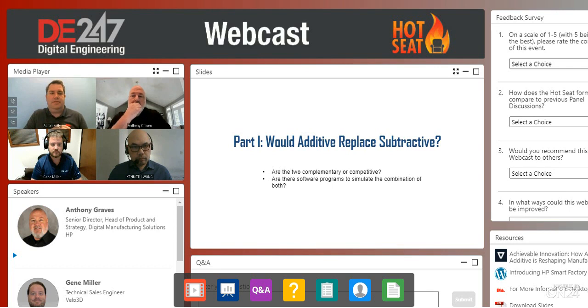If you put that together, for example, Anthony brought up a mold design. Some parts need deep pockets cut out. And in additive, you don't pay for the removal of that pocket. You don't have to have tooling doing the removal of that pocket. You can have an additive part created, and you're only using the material you need. And when you need those fine surfaces, those high precision tolerances, you can then take that part and move it over to your CNC machine, and you can finish it. That's a perfect example of how the two technologies complement each other, and it's to solve those business problems.